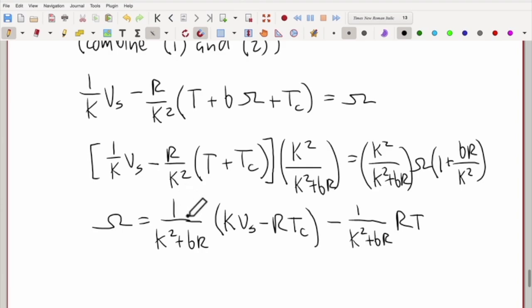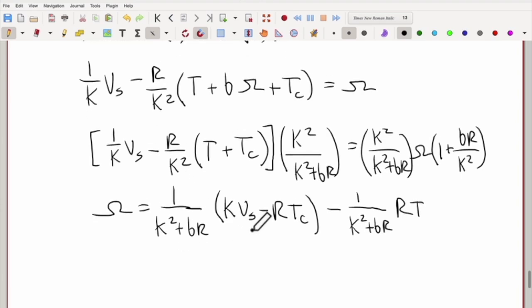So what we can do now is we have this about the torque produced by the motor and these other things that are kind of inputs or fixed like this. So one thing we can say is, well, if our torque is 0, then this term drops out, and then we can conclude that this guy is this free running speed that we wanted a relation for. So this is our free running speed here, right? Just set this torque equal to 0, everything else is just constants, and we're left with this. Omega is equal to omega f. So this is omega f.